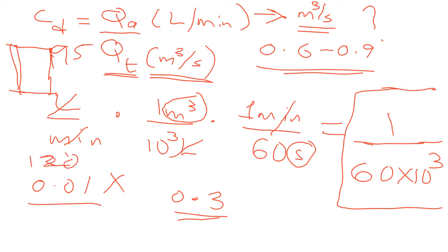And when you use 120, it will affect your result throughout. Okay? You use the depth gauge because you will be subtracting. Depth gauge gives you 95, and then when there is flow, you use the depth gauge to measure this. And when you subtract, it gives you the depth of the water flowing. Okay? And that is the correct thing to use, not 120. When you use 120, if you check, I will cycle that 120 because it will affect your result all along.